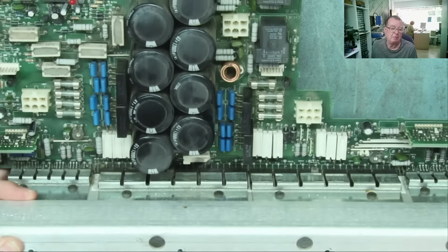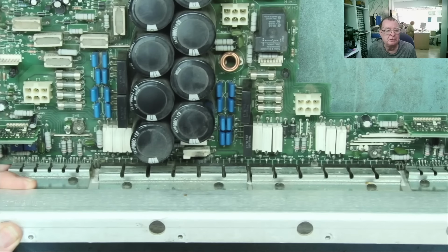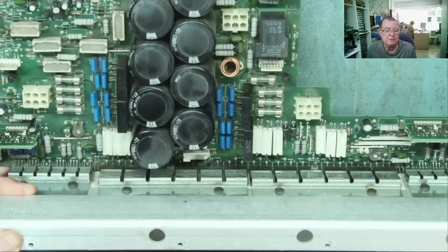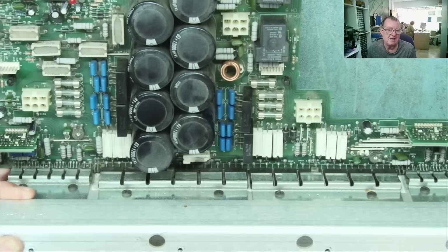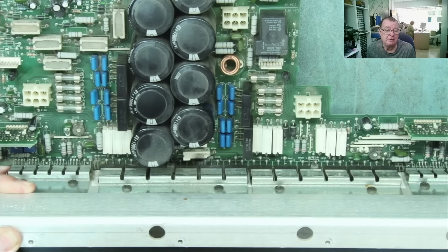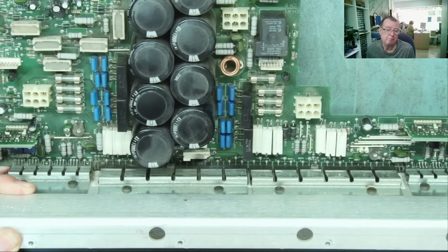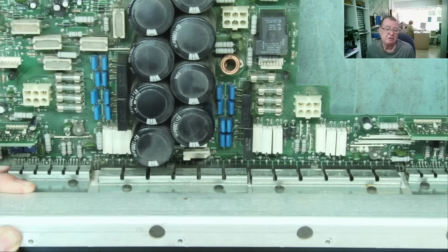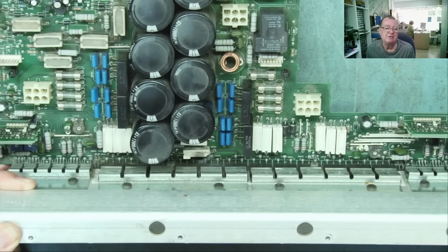Normally when power devices fail, they do one of 2 things. They either go short circuit or they go open circuit. The ones that go open circuit are usually visibly open circuit because they explode. Finding short circuit power devices is generally not difficult. There are challenges in multi-phase circuits like that VRM on the motherboard I was showing you, and I've made videos about that, so I won't specifically go into it.